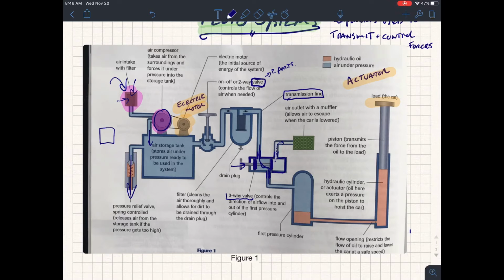So this valve controls the flow of the fluids. We can turn it into two different positions, one position and the second position, when the valve checks here are moved into this position. So two different positions, three ports, and you'll find that valves are often described using that language. How many ports and how many different positions can we have?